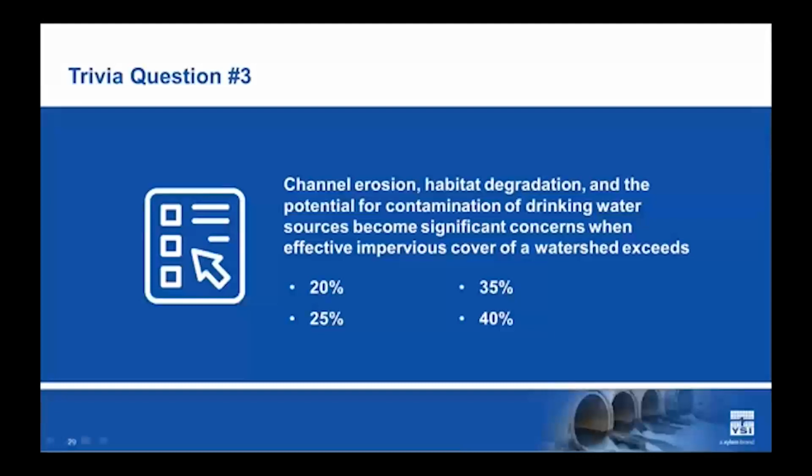One of the things that I like about bubblers, first of all, they are super easy to use, and they're a little easier to install as well. But the other nice thing is a bubbler just has water pressure pushing that bubble out of an orifice tube. If the water goes dry, if you're working in one of those intermittent tributaries that only has water in it during stormwater, a bubbler is an awesome solution because you don't get any interferences.